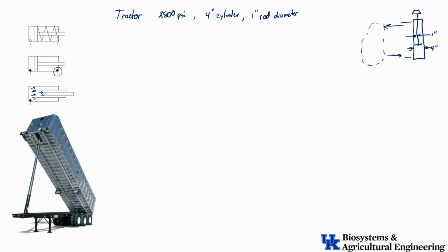So we have 2,800 PSI available here to lift the load, but when that thing is moving, we're going to have 500 PSI over here. So 2,800 down here, 500 PSI back there resisting that. Oh, so if I've got pressure resisting the motion of that, that's going to limit what I can lift, because I've got this pressure down here creating force up, but I also have the back pressure that's creating a force down. That force down is going to be acting over a different area because the rod is taking up some